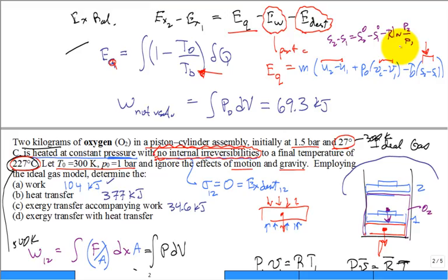Look good? Do I have an error in it? Remember that equation out of Thermo 1, how to calculate the entropy change for an ideal gas. Well, right away, our pressure isn't changing, so this term is very simple. The natural log of 1 is 0. Very good. And then where do we get this S naught?